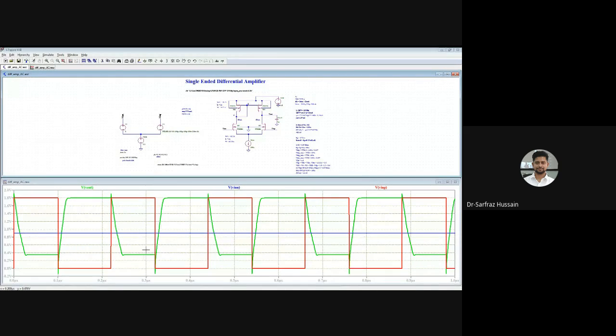And when an output is increasing, going from 0 to the higher amplitude, or we can say from the lower potential to a higher potential, then this will give us the positive slew rate. Now what we will do is add up these two and take the average of these two, and that will give us the actual slew rate value. So we need to make sure what slew rate we are considering.